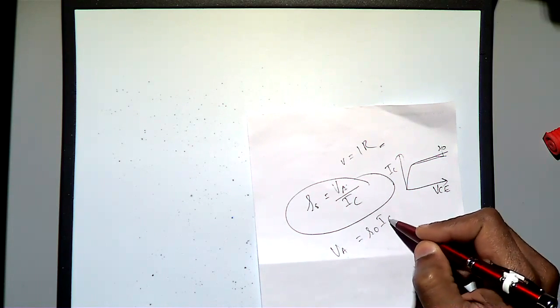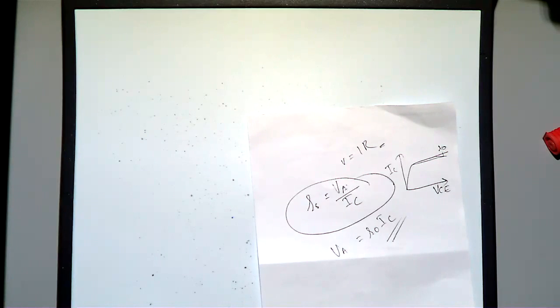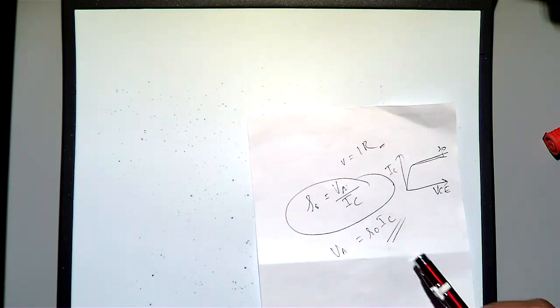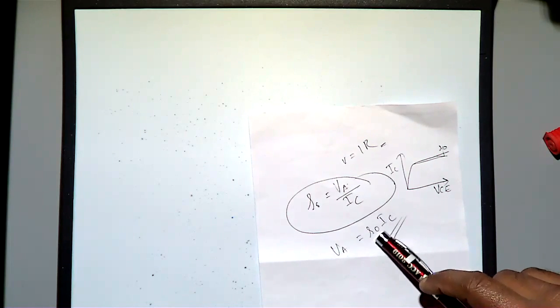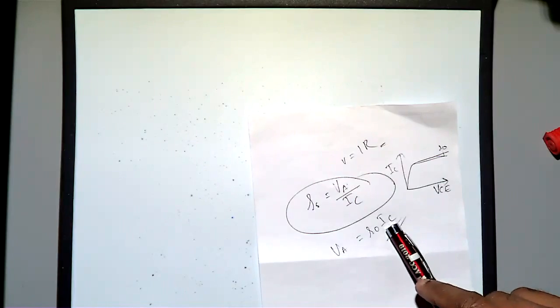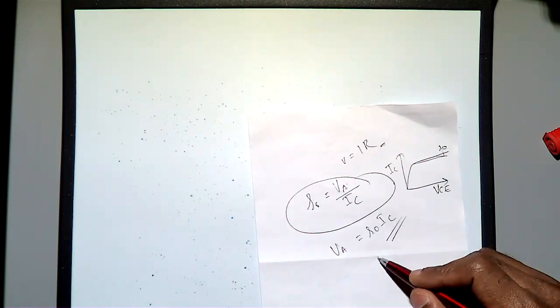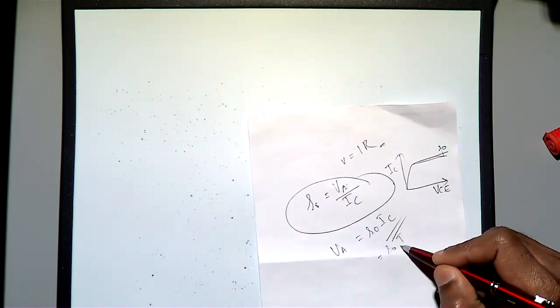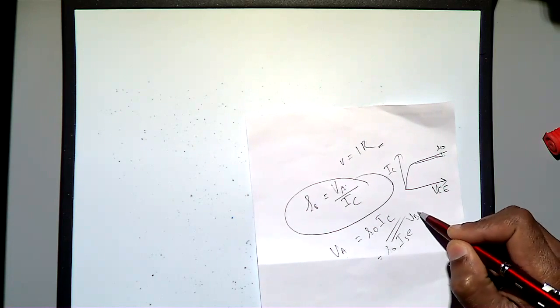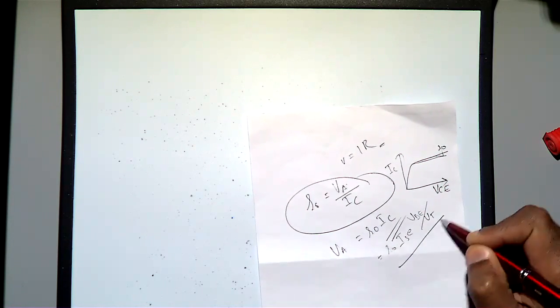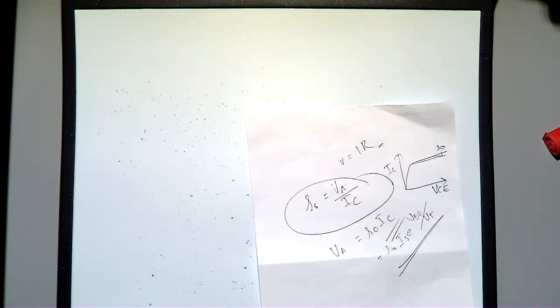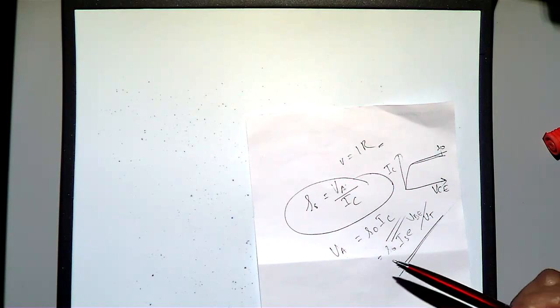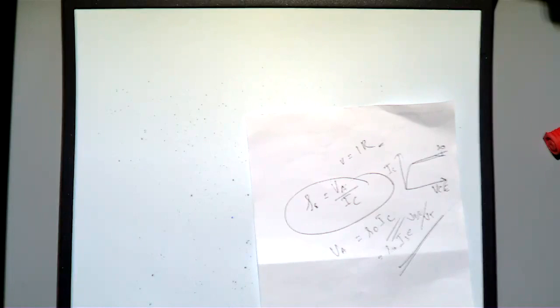So what is the early voltage? VA is equal to RO into IC. So this is the output impedance, and then you are getting the collector current. Maybe I can write IC as IS exponential VBE by VT for the case of BJT, because IC is controlled by the VBE. And then if you look at this one, how will you control it?